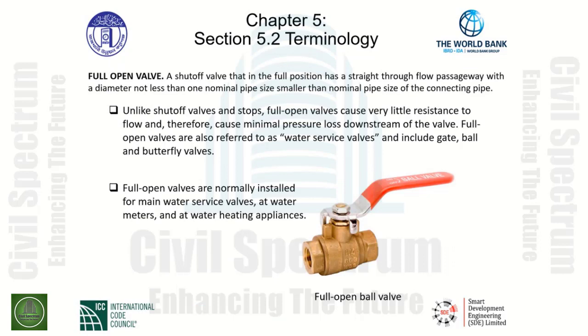A full open valve is a shutoff valve that in the full open position has a straight through flow passageway with a diameter not less than one nominal pipe size smaller than the nominal pipe size of the connecting pipe. Unlike shutoff valves and stops, full open valves cause very little resistance to flow and therefore cause minimal pressure loss downstream of the valve.